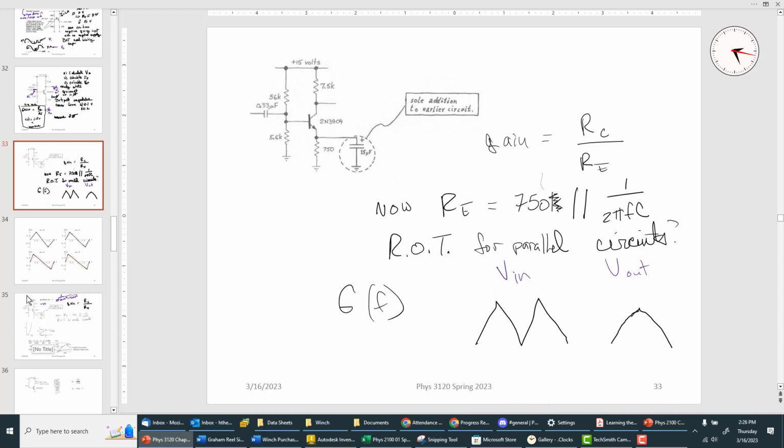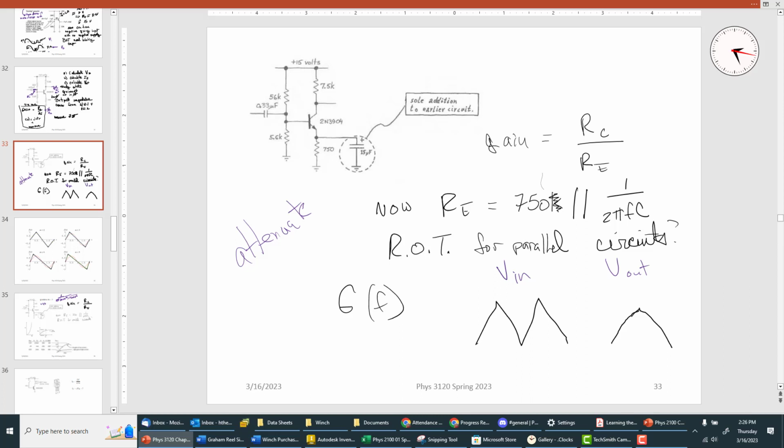So you have to use your 40 dB attenuation on your function generator. Some of you have 20 dB, some have 40 dB. And it's a switch or a button to press on your function generator. You just ask me and I'll show you.